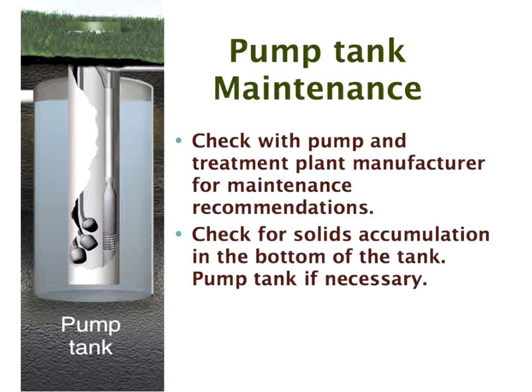Well, okay. Pump tank maintenance. The pump maintenance is talk to the pump manufacturer. Check for solids, as we spoke about before. Solids will build up at the bottom. And then, of course, also check your floats.